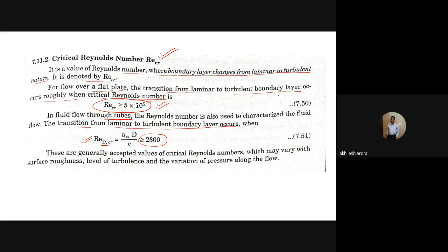The moment it is flow over cylinders or a sphere, according to the geometry, the value of the critical Reynolds number will vary. So if somebody asks you in some interview what is the critical Reynolds number for transition from laminar to turbulent in case of a flat plate, the value is different than 2300. 2300 is for the pipe flow only.